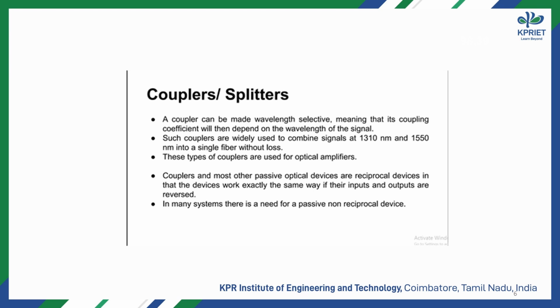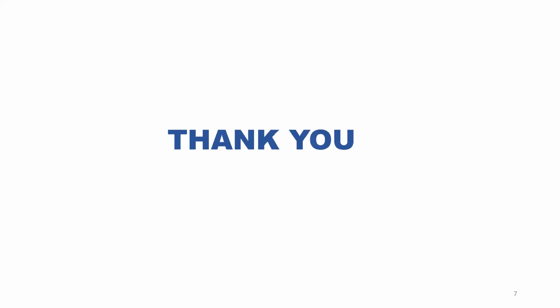Couplers and most other passive optical devices are reciprocal devices, meaning the device works exactly the same way if their inputs and outputs are reversed. In the sense, if I connect the input and the output ports in reverse, the same behavior will be repeated in an opposite manner. In many systems there is a need for a passive non-reciprocal device. Such kinds of devices are